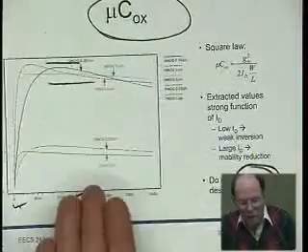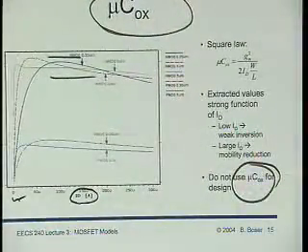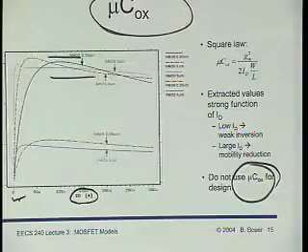Yes, these effects include velocity saturation. Oh yes, this includes everything, because I haven't done a real measurement. I use SPICE here, assuming that SPICE has absorbed the real behavior of the device, and so instead of running a real measurement, I just run SPICE to effectively measure.